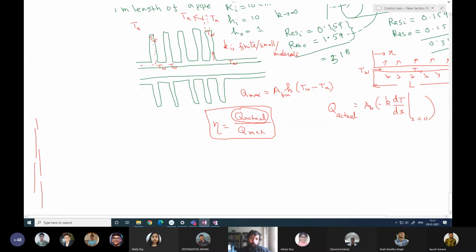So now what we'll try is that we'll analyze a single rectangular fin, the simplest kind of fin with the simplest boundary condition, and obtain the expression for eta, that is the fin efficiency. And for other cases also such analysis is possible, a little bit complex, we'll not do it in the class. But those are already done, and fin efficiency for different geometries are available. So we'll use those charts and tables.